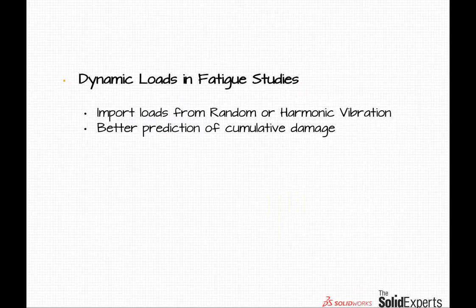Previously, all we had was static study options to import into a fatigue study. So we could only take results from our static studies, simulations, and use that to calculate our fatigue studies. Now in 2015, we have the ability to import loads from random or harmonic vibration analyses.